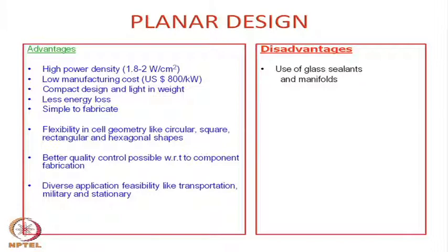Unfortunately, several glass compositions are available for this kind of purpose, but none of them are fully satisfactory. Either there is breakage because of the thermal cycling, or there are reactions between the components. So, that problem still exists, but a lot of development has taken place, and one can use some of the glasses available. Many of these glass compositions have been patented by different glass companies, including SOFC from Germany.